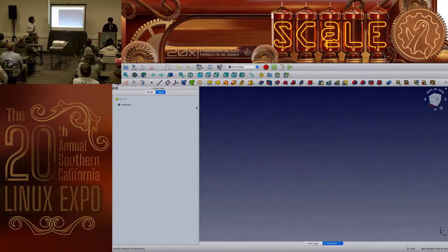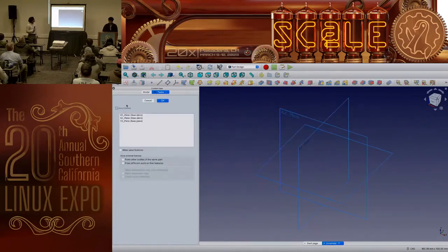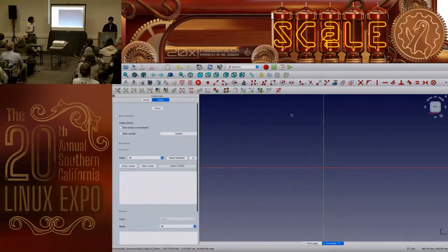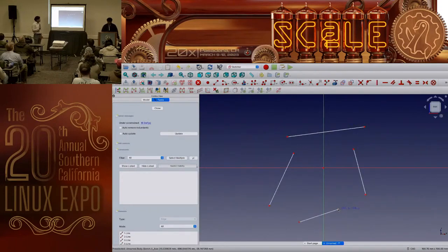So obviously, we're going to need a square, right? So when you first create something, you want to create your body and create a sketch. What Create Sketch does, instead of going straight to 3D, you're just going to have a simple sketch. So you could choose whichever plane you want, but for this, we'll choose the XZ plane. So of course, I'm going to need a square, right? I could automatically just use Create Square, but for the explanation, we're going to go line by line. So, of course, a square, 4 lines. I know you're wondering, what is this? This is not a square, right? So someone describe a square to me.